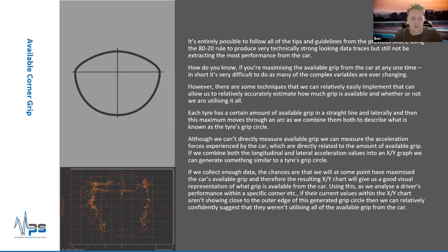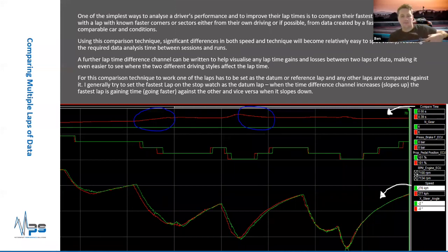Then you look at whether it's predominantly under braking, trail phasing, or acceleration, and you can work your way down alleys and narrow down exactly where your performance deficit is coming from. So all those techniques are looking at a lap of data in isolation.